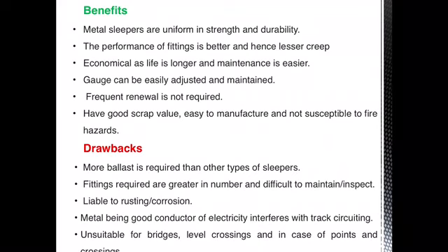easy here. The gauges can be easily adjusted and maintained, and frequent renewal is not required in the case of the metal sleeper. Since the metal also has a good scrap value, it is easy to manufacture, and it is not susceptible to any kind of fire hazards.